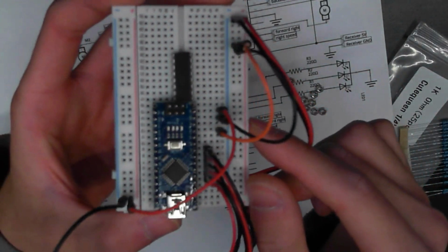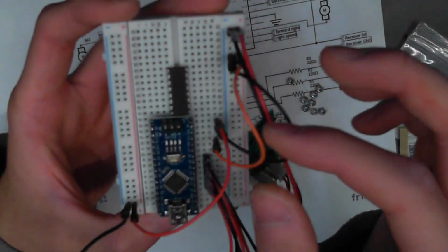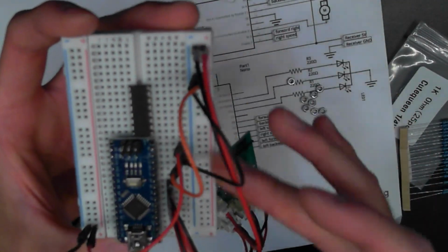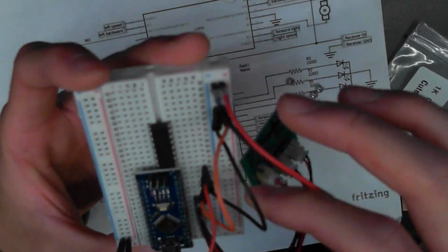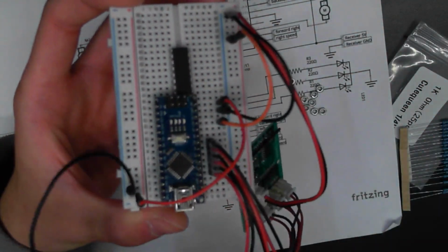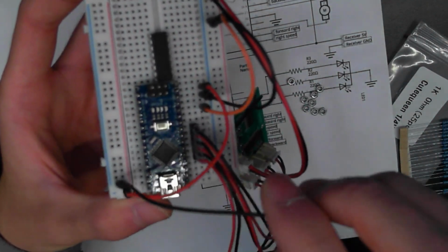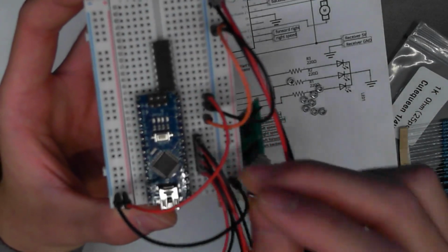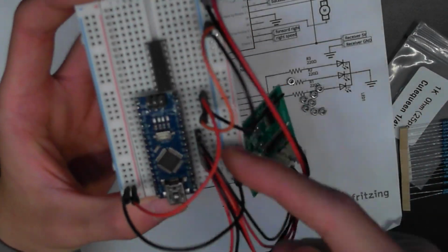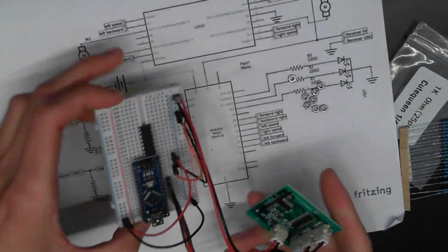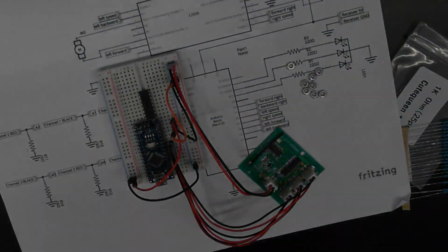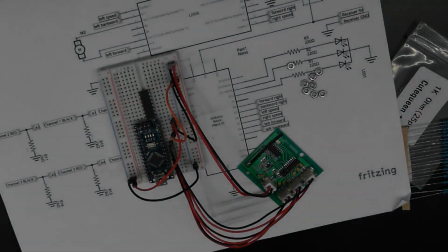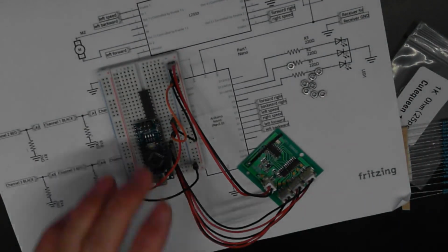And then again, just to recap from last workshop, this orange wire, or whichever wire you've used, is your 5-volt line, which connects to the right side of the breadboard. And then the ground, we want to bridge them together as we want them to both have the same ground reference. So I'm going to bridge it over like so. Both blue lines are joined together by this black wire. So that's the Arduino and the receiver. Now let's get the rest of the components wired up.